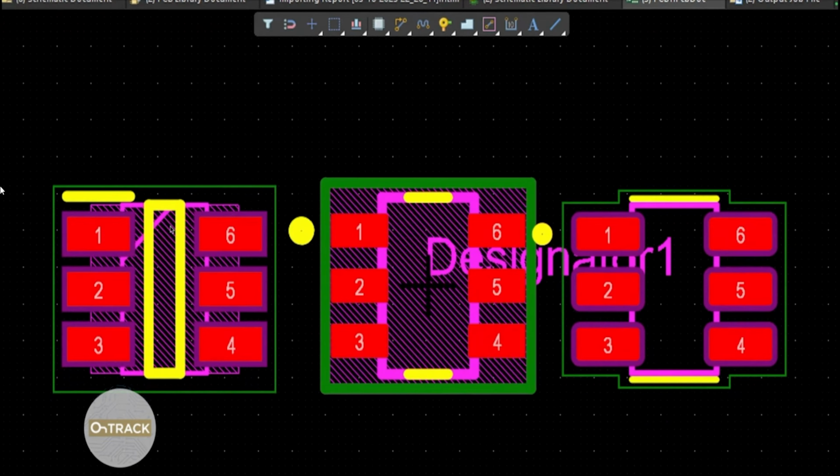Not really a question, more of a comment from Peter, but he does bring up a couple of really good points about solder mask expansion, which I think a lot of folks don't think about, and that is the size of the leftover solder mask sliver. If you take a look here on screen, you will see that we have 3 footprints, all for the same component, from my podcast episode with Elizabeth Bustamante, and you can see what the solder mask sliver is just by looking between adjacent pads. You can see that within these footprints, you'll have some leftover solder mask between the pads due to the solder mask expansion around each of these copper pads in these footprints.